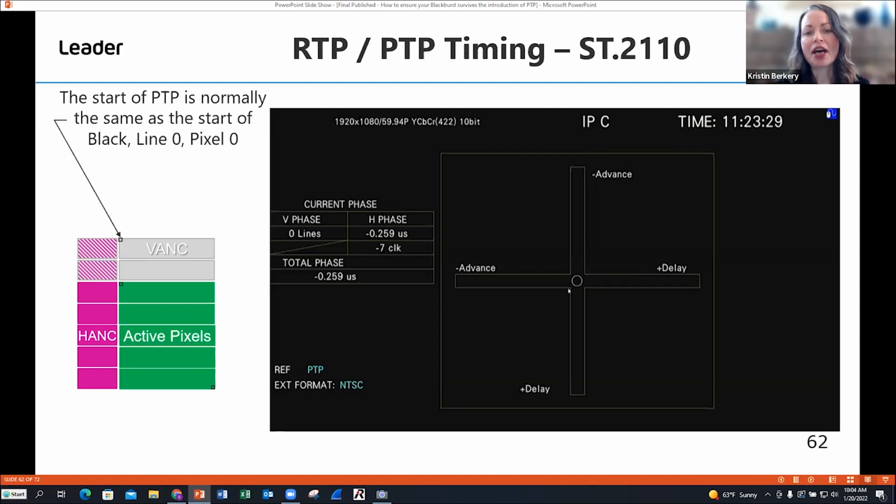How would you suggest we lock two grandmaster clocks in lockstep if there is no GPS signal available? And then the second part of that question is, how can we guarantee the baseband sync coming from each grandmaster without GPS will fail over hitless in the ACO? Without GPS, you're going to be in a clock class 248.